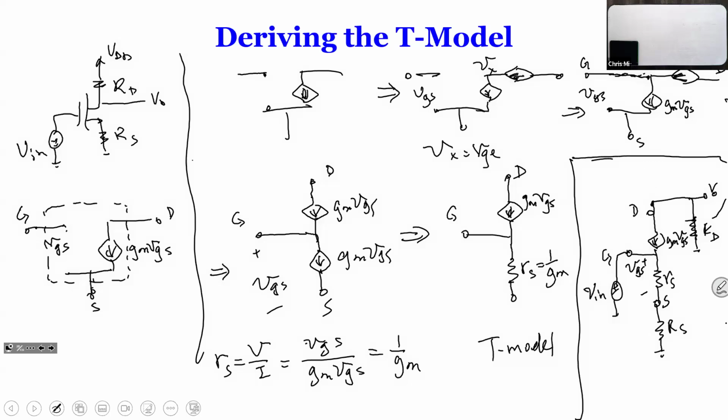Okay. So you see here, clearly Vin is not VGS. That's important. If you treat Vin as VGS, you're almost totally wrong for this output. Okay, you might say, why does this make it simpler? Well, if you look at this one here, it is ground. So it's a voltage divider, right? So your VGS is going this way, and the voltage at these two are going to be divided. We can find the voltage at S and then subtract it from Vin.